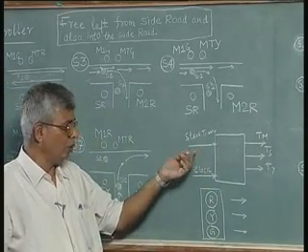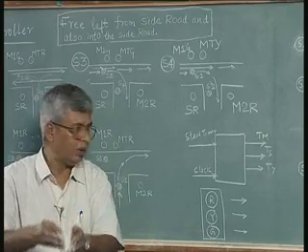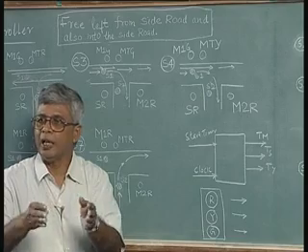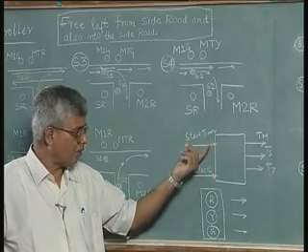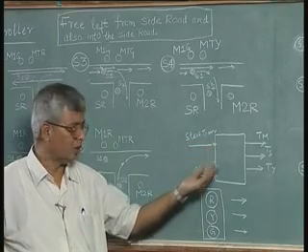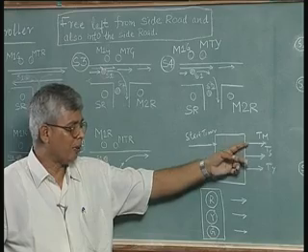Now, whenever we want to time how much time the traffic should be on for the main road, how much time the traffic should be on the side road, how much time yellow should be there, all that will be controlled by a single timer. Every time we want a timer, we can start the timer. Of course it is clocking, so it will be a simple counter, and whatever time you want you can tap it from here.